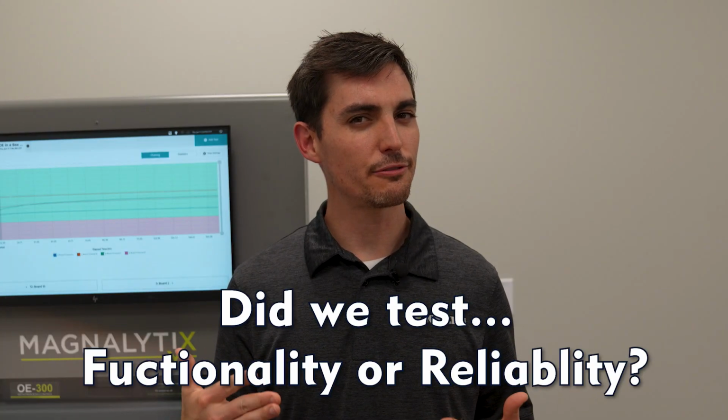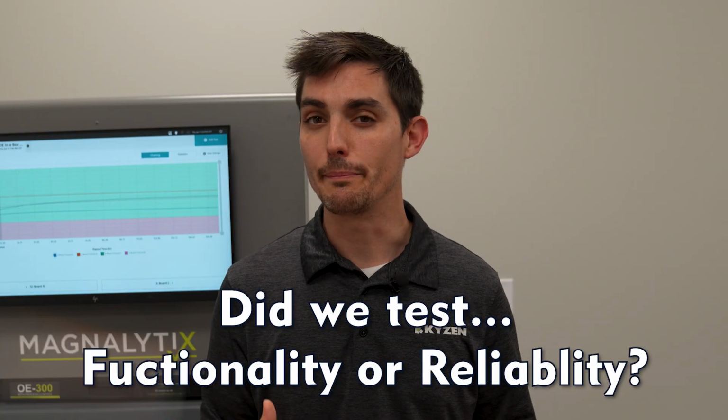If your goal is simply to verify the assembly, electrical testing is sufficient. But if your goal is ensuring long-term performance, preventing field failures, and generating objective evidence of reliability, then you need testing that reflects degradation mechanisms. And in contamination-driven systems, SIR is one of the most powerful tools we have to detect those risks before they become failures. So the next time your product passes everything, take a step back and ask, did we test functionality or did we test reliability? Because those are not the same thing, and in this industry, that difference matters.